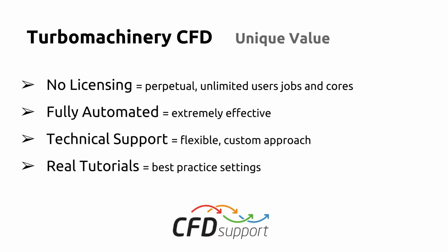So in Turbomachinery CFD, the user has no doubts about the best practice settings. Real machines that are already preset are included. So basically you can take one of those tutorials, and you can just replace the geometry or the model with your own, modify the physics, modify the settings, and run the simulation. It's already prepared to start your own simulations.